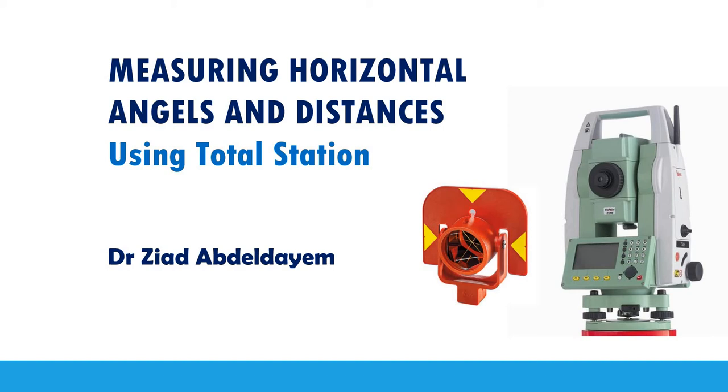Today I'm going to focus on how to measure horizontal angle and distance using total station. And the method for measuring horizontal angle is the same using total station or even theodolite. So you can apply the same method to measure a horizontal angle to a very high level of accuracy using theodolite as well. So let's get started.